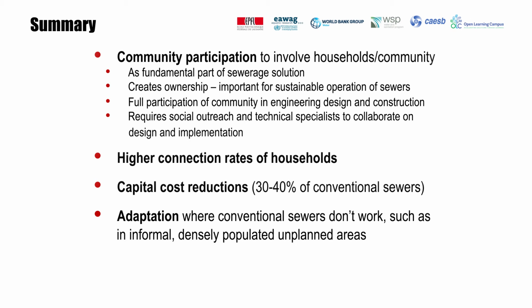The adaptability of the condominial approach to local conditions enables the provision of sewerage service where conventional solutions would not be possible. For example, in informal, densely populated, unplanned, peri-urban settlements. However, the condominial approach can be equally applied to formally urbanized areas. In the district of Brazil where CAESB works, condominial sewers have been successfully implemented in all types of urban settings, poor and rich alike.